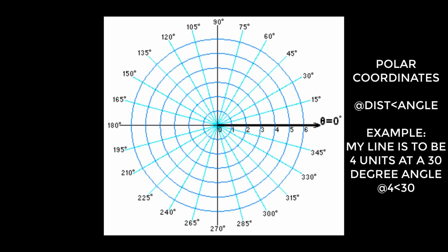We always work in a counterclockwise direction. So wherever my point is, and I want to go to the next point, I work off a 0. So if my angle from 0, in the very center at 0,0, is pointing down into the bottom left quadrant, I'm going to come off a 0, so my number will be somewhere between 180 and 270.